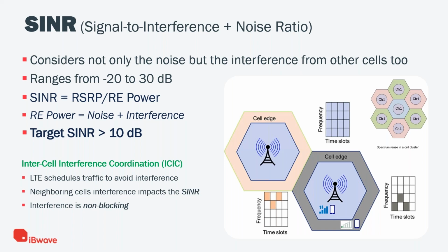But also Wi-Fi is listen before talk. So if there is something I can understand, then I shouldn't talk, I should wait. In LTE it is different. Since it's a licensed spectrum, usually there is not much interference that is non-3GPP. I would evaluate what the other transmitter is transmitting and use other resource elements instead of just waiting.